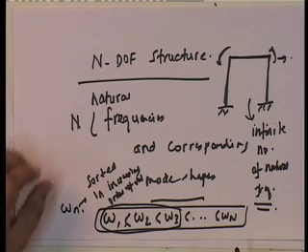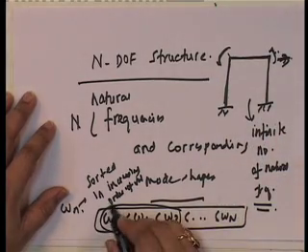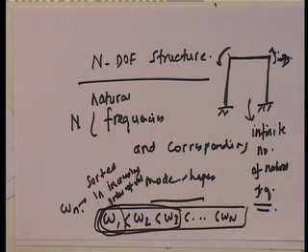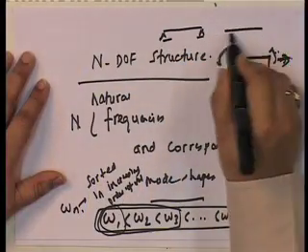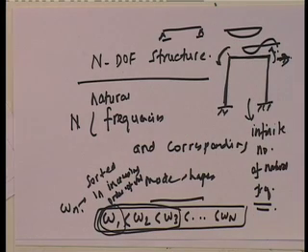Now, I said that if I use the lumped mass formulation, I only get a single degree of freedom. These two also disappear. Which one do I get? I actually get only this one. Approximation. And that is the beauty of this, that all we do is get a good estimate of the natural frequencies and the corresponding shapes of vibration, because whenever you have a continuum, it has a shape of vibration. For example, it can vibrate this way, it can vibrate this way, so each has a shape associated with it.